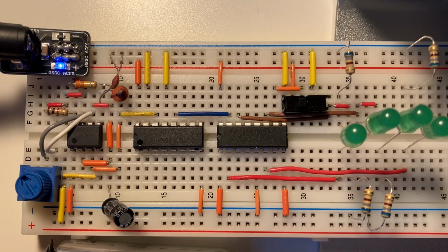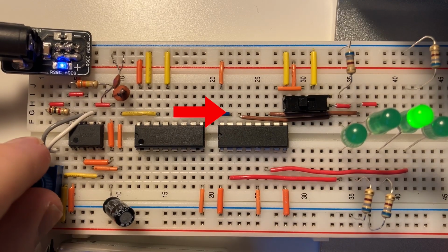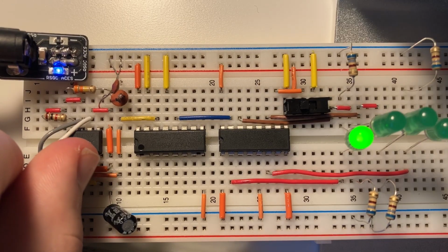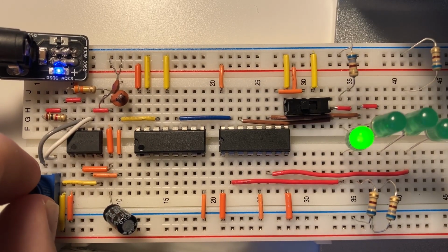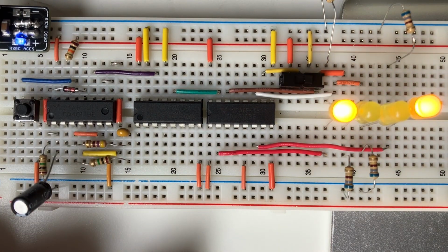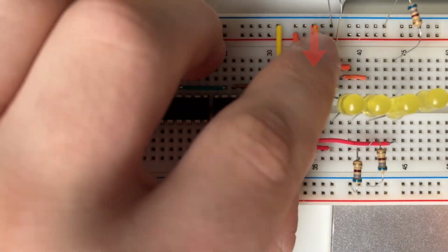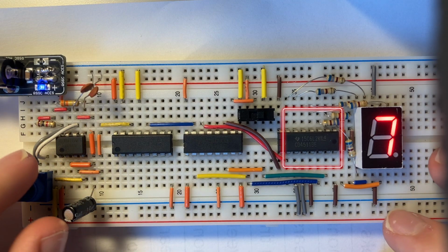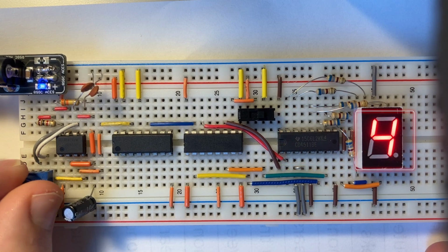The binary counting includes all the previous steps, with the 4017 divided by 10 going into the clock signal of the 4510. The 4510 then provides each LED with a different value, 1 on the furthest right and 8 on the furthest left, with a different value in between. As well, with the switch, it can count up or down based on whether the switch is connected to the positive or negative rail.